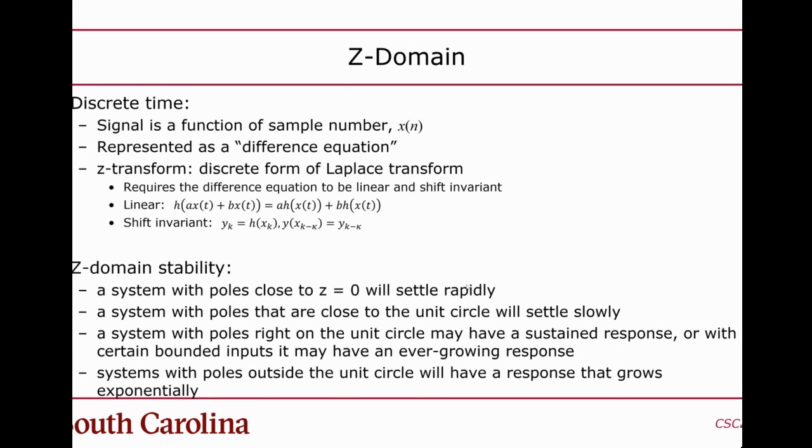The first thing is that determining whether a Z domain LTI is stable is different than in the S domain. S domain is really easy. You just look for the poles, which are the roots of the polynomial in the denominator. You find the poles, and as long as the poles are in the left-hand plane, the system is stable, right?